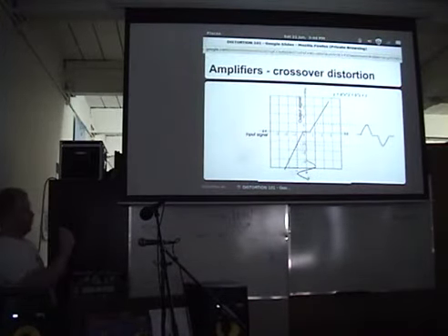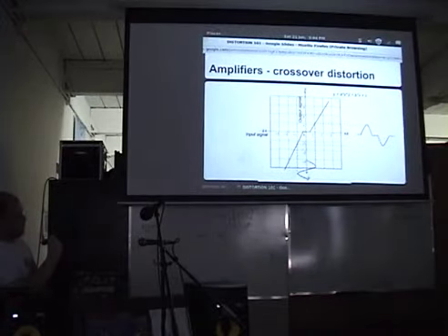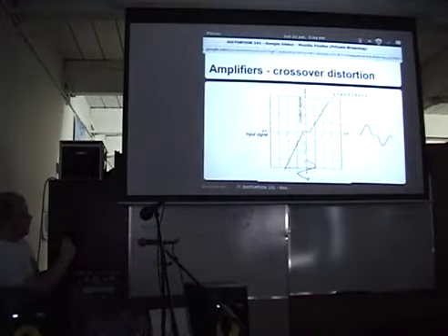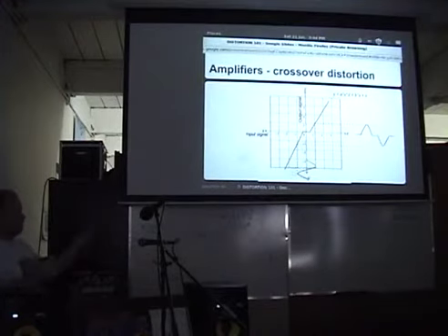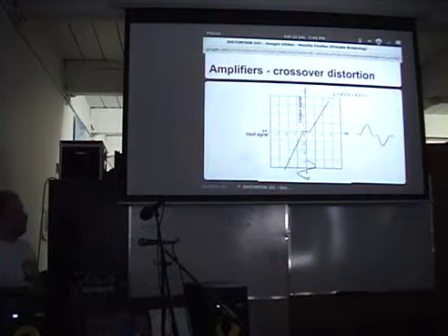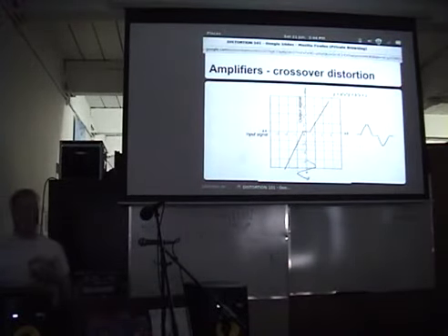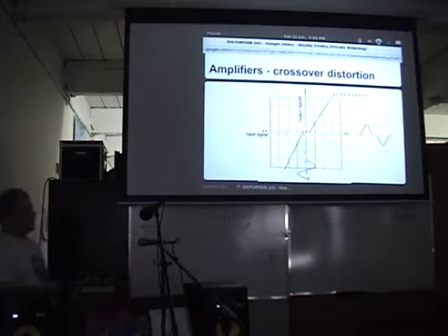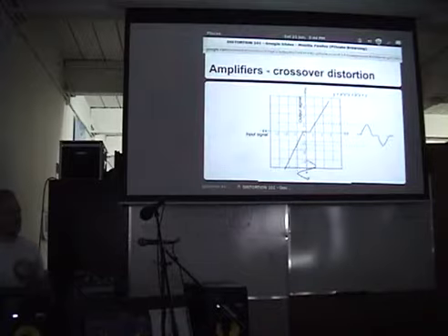And there's got to be some switchover time between them. So that's when you introduce this many-to-one mapping in your transfer function, where for the little values in the middle of my input signal, they just make a flat area of the output. This is usually reflected quite a bit in the total harmonic distortion rating you might see on a hi-fi amplifier. And this isn't really something you use in guitar audio circuits. It just sounds bad in general and should be avoided.